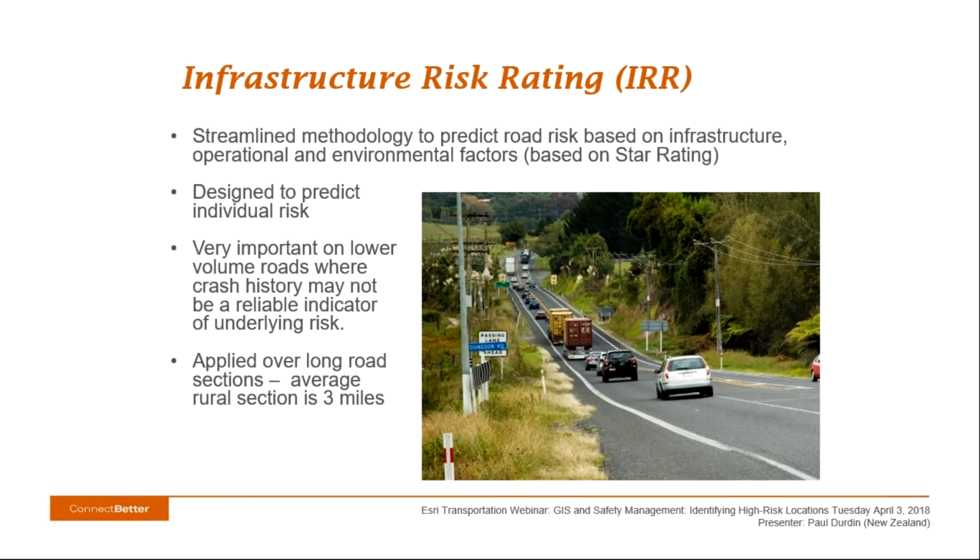It is a predictive road assessment methodology designed to assess risk independent of crash history, and it is based on star rating. It's designed, however, to utilize existing data sets and omit the time-consuming and expensive collection of data involved in star rating. This approach is very important on lower volume roads where crash history may not be a reliable indicator of underlying safety risk.